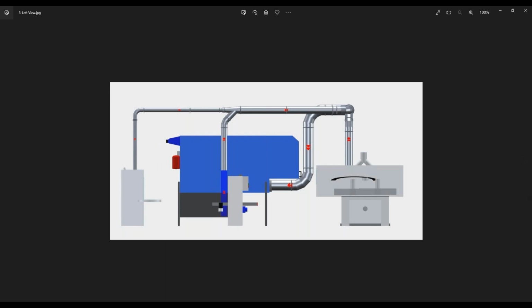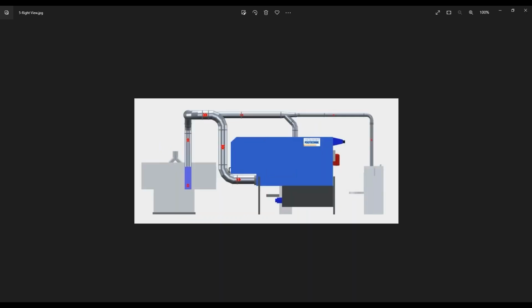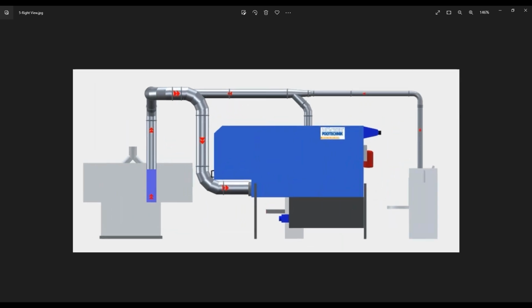So now that we are looking again at the left view, I want you to, in your mind, imagine and think, what would this look like from the right view? And there's our right view. And once again, this shows information here and here that the left view hid from us, but there's information hidden by the body of the collector about that drop, as well as the body of this edge bander about this drop to the edge bander.